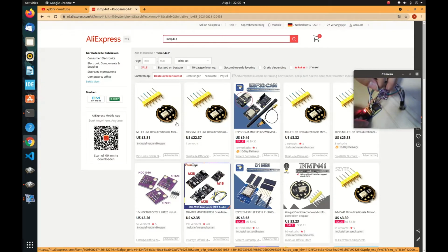In order to connect this speaker, we also need an amplifier to accept the signal from the I2S interface output, amplify it, and send it to the speaker. The one I'm using here is also quite popular. It's from the Maxim company, called the Maxim 98357.